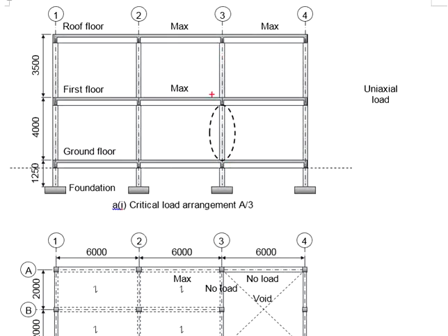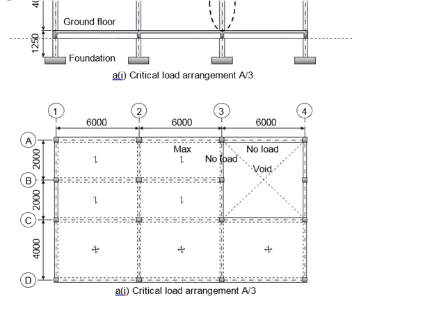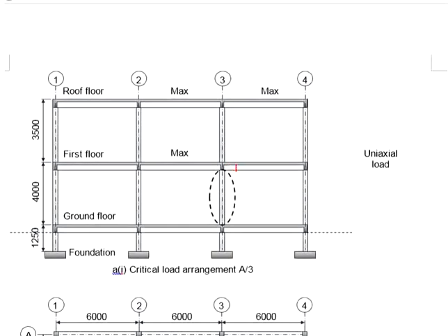You expect no loads from the incoming beam, and you also assume there is no load here. Why is it so? It is because when you view from the first floor key plane, this region is a void. As a result, you do not have any load here. By having this side to be the maximum load, that will give you the largest possible moment acting at this end. Because of the UDL here, there will be fixed end moment. However, this side, there is no fixed end moment.